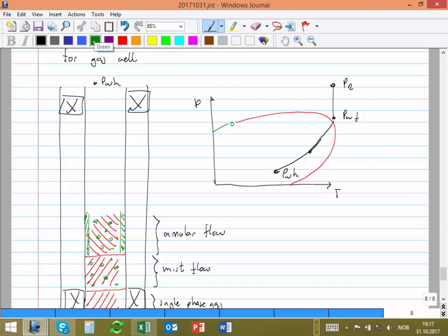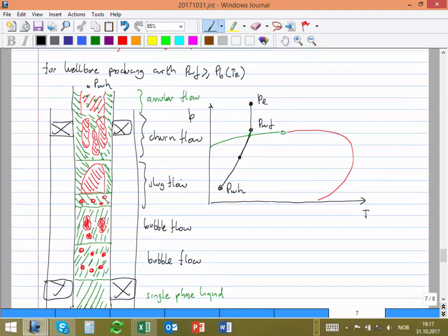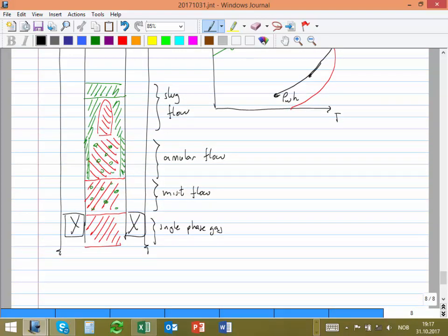Then if we continue, then we are in trouble. Actually, we will have some pockets of gas and some pockets of liquid, and that we call slug flow. Okay. So if you see, it's like the opposite. If we put one next to the other, then we will have the full range from full liquid to full gas. Okay, if we put one on top of the other. But basically that's what happens, and that's the complexity we're dealing with when we are talking about multiphase.